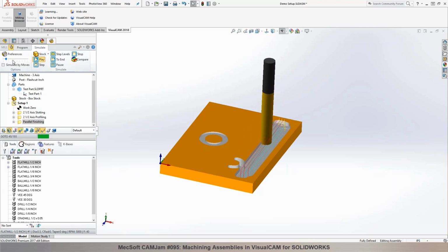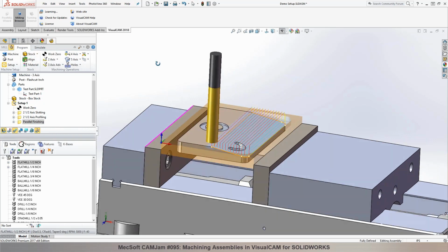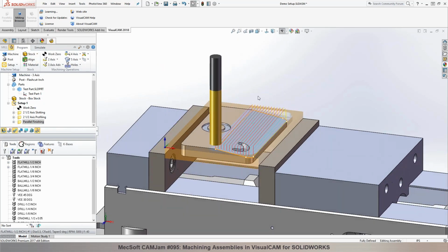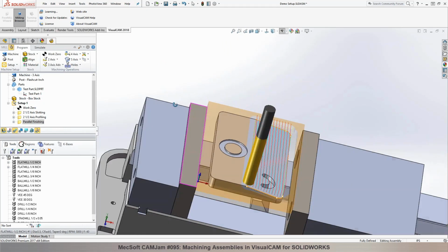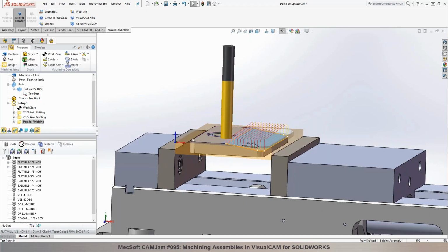Okay. So this is just a finishing pass. If you want to do roughing and then a finishing, we can certainly do that. So since there wasn't too much material being left, that's where we do rough and finish, right? So in all these processes, what you notice here is we are only machining the areas we picked. It was not violating any of the areas, right? So you wouldn't run into any interference or collisions. Now, over here, you would want to relieve this material by cutting out a profile in here, right? So this is 1/2 inch, and you probably would not want to go all the way through, right? So you may want to leave like a tab or bridge, so at least the part and the stock are still intact, right?